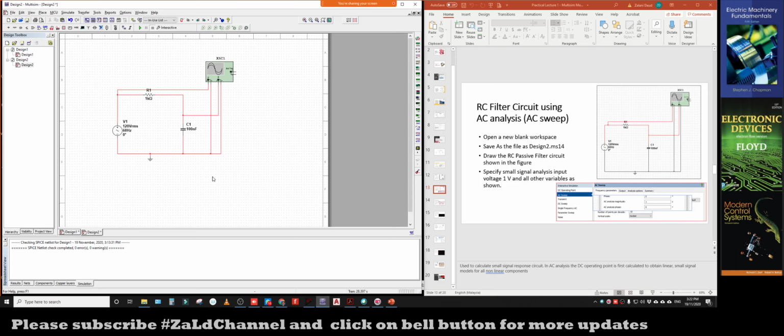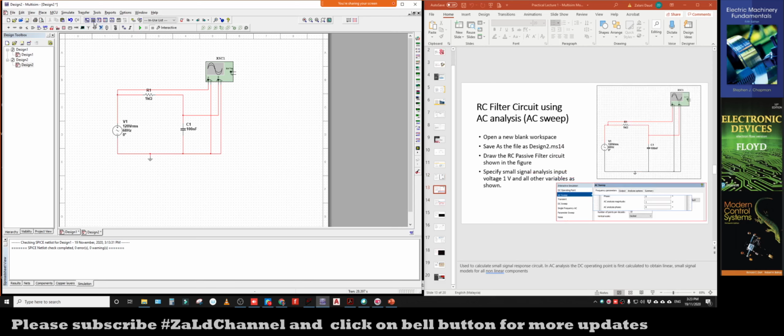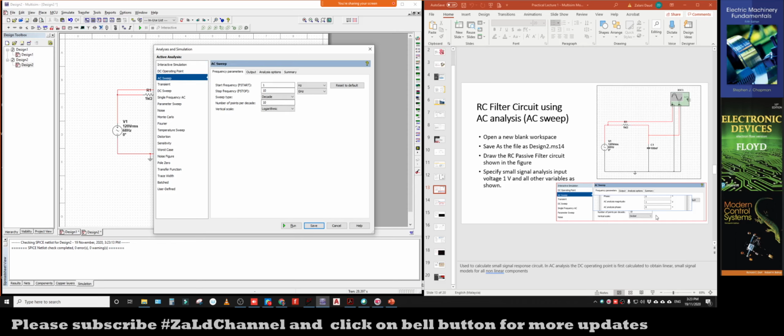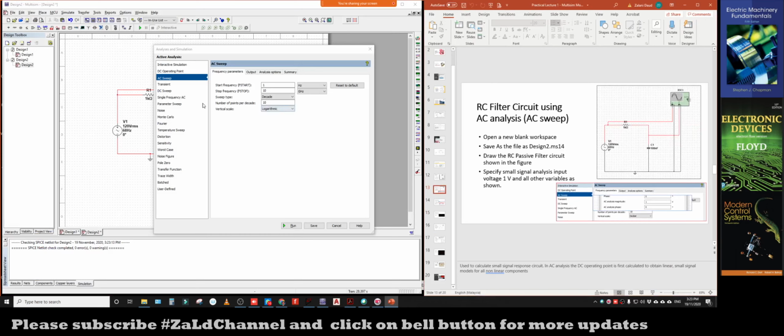When you do the simulation, now we are going to use the AC simulation, which is the AC sweep. If you follow these slides, you can do it. I'm going to set the simulation settings: go to simulate, then analyze and simulation. The interactive simulation analysis will pop up like this. So we just select the AC sweep. You can follow this part of the slide, where the settings are. In AC sweep, we are going to do the simulation.